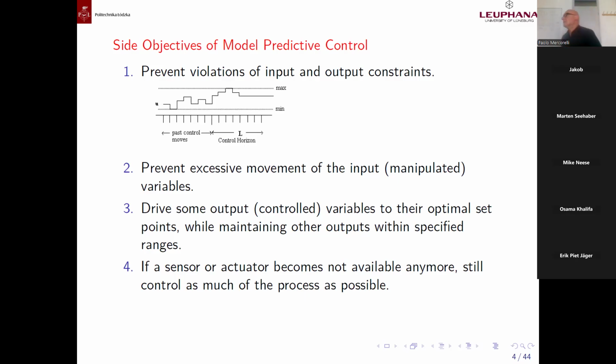And this means in some books they speak about just a control horizon. In any case, the control horizon is always less or equal to the prediction horizon. It's clear because I can control just if I can predict. This means the control horizon is less or equal, very often equal, to the prediction horizon. Therefore, this picture you can find in many books.